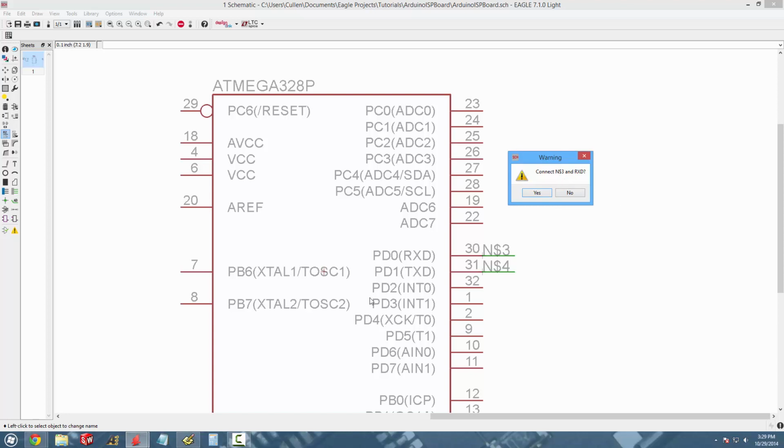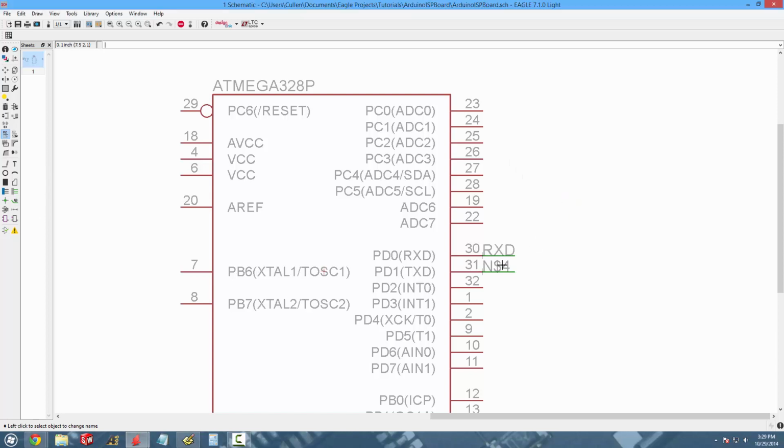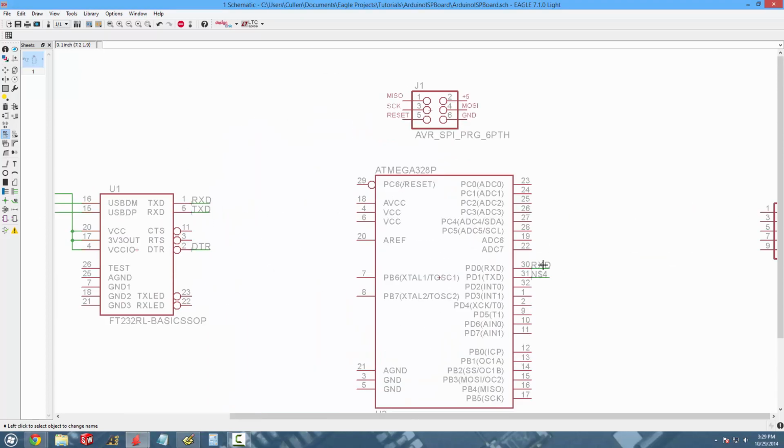So we haven't seen this before yet because there hasn't been two different nodes that we're connecting. So it's asking us if we want to connect this with the other pin that's over here already connected. So we're going to say yes. So now, even though these aren't physically connected, because we named them, they are the same pin. Like if I go to show here and I click this, see how they both highlight? It makes the schematic look much neater. So I definitely recommend you guys use that tool instead of literally drawing wires everywhere. I hate it when it looks so disorganized, in my opinion.